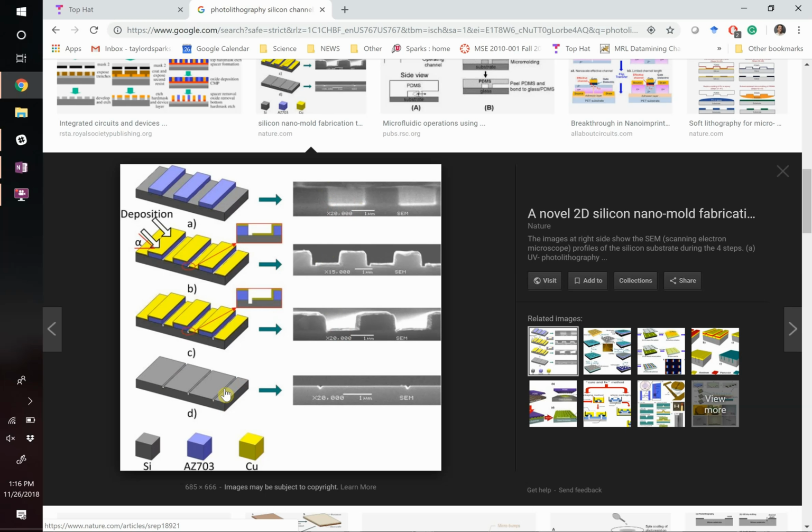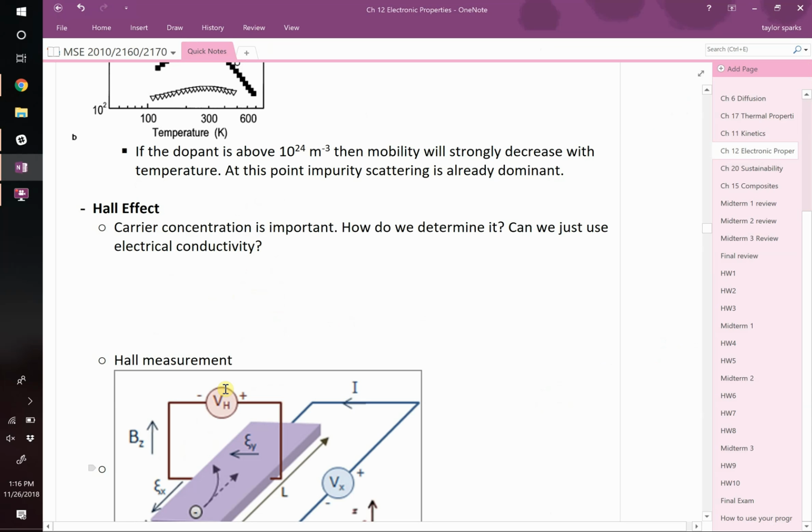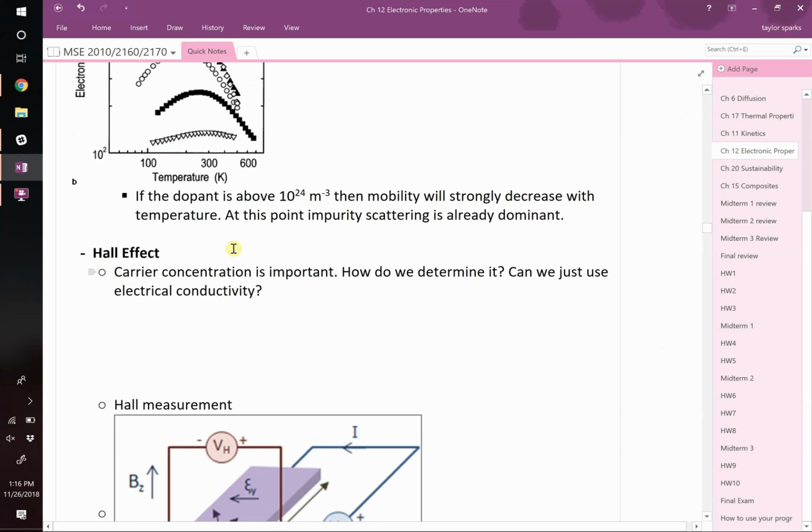It all had to do with light, right? We're going to get to how we got to doing that in a minute. Okay? So they heat it up. They'll paint it on the surface. They'll sputter it. There's something called ion injection, where they take ions like phosphorus or boron, they ionize them, they put a big electric field between your substrate and some cathode material, and then they bombard them into your sample. They just crash them into it. So all these have sort of pros and cons in the distribution that you get.